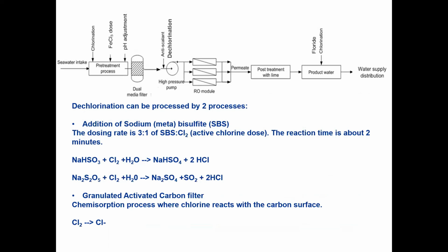So people want to know: after you chlorinate it, you have to dechlorinate it because chlorine damages your polymer membrane through oxidation, right? What to do? So this is dechlorination.